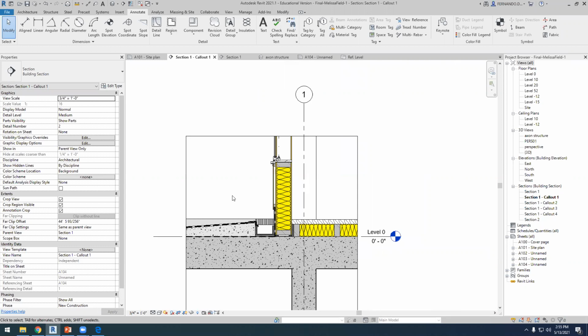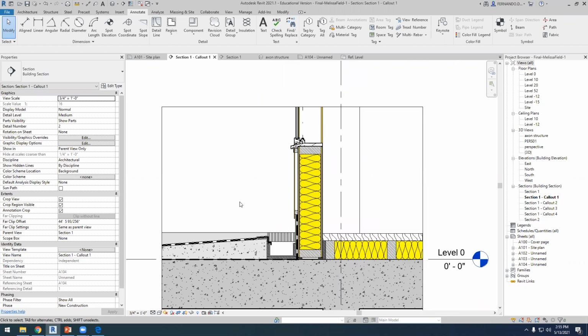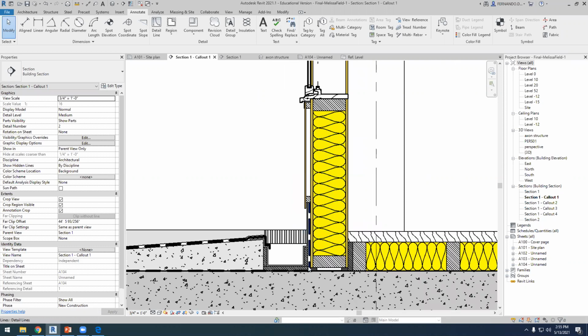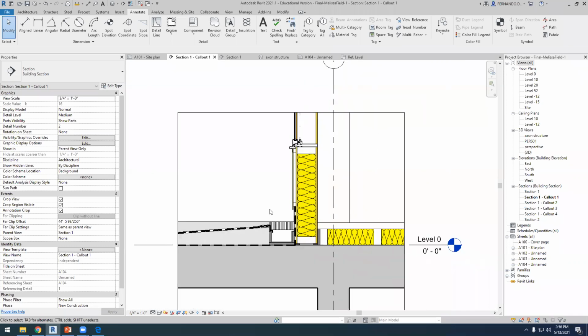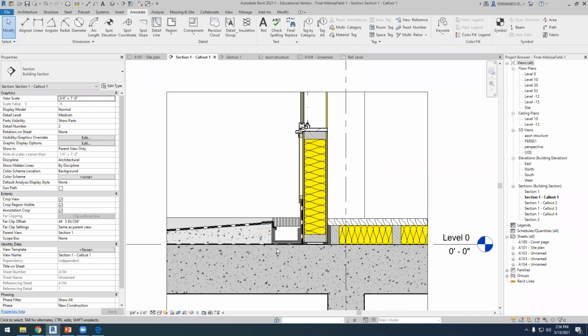Yeah, so I think if we think that we are water and we want to enter the building, we need to find a water barrier, we always have to find this, unless we have a vertical element. If there is vertical, water goes down immediately. But if it's horizontal, we need to enter that building, so we always need to find a water barrier. And I think in this case, we have all of them.